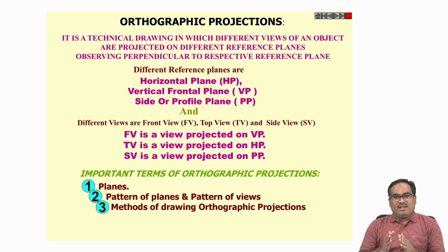The different reference planes are the horizontal plane, vertical plane, and side or profile plane. The front view is projected on a vertical plane, the top view is projected on a horizontal plane, and the side view is projected on a profile plane.